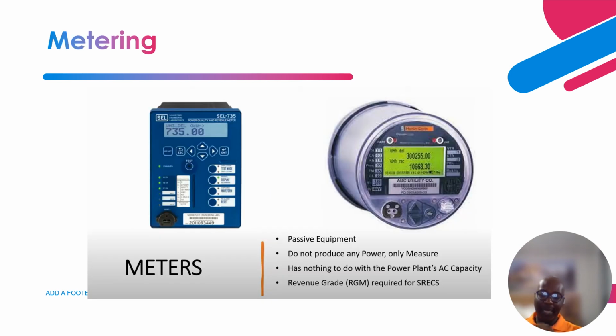And at the point of interconnection, the grid interface, the point of common coupling, you need metering, and you utilize the SEL. A typical one that they are using is the SEL 735 for metering, so that the amount of power you're sending to the grid will be paid by the utility company. And these are passive equipment. They are not active. And some of them can be revenue grade and non-revenue grade.